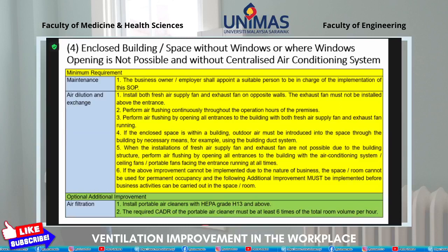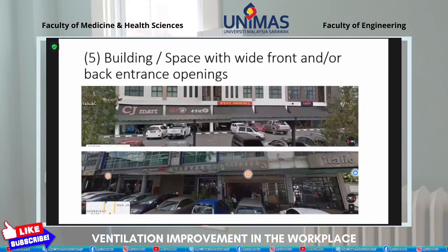So if they need to use it for short-term occupancy, then they must install a portable air cleaner with HEPA grade H13 or above. And for this kind of environment, the required CADR is at least 6 times the total room volume per hour.